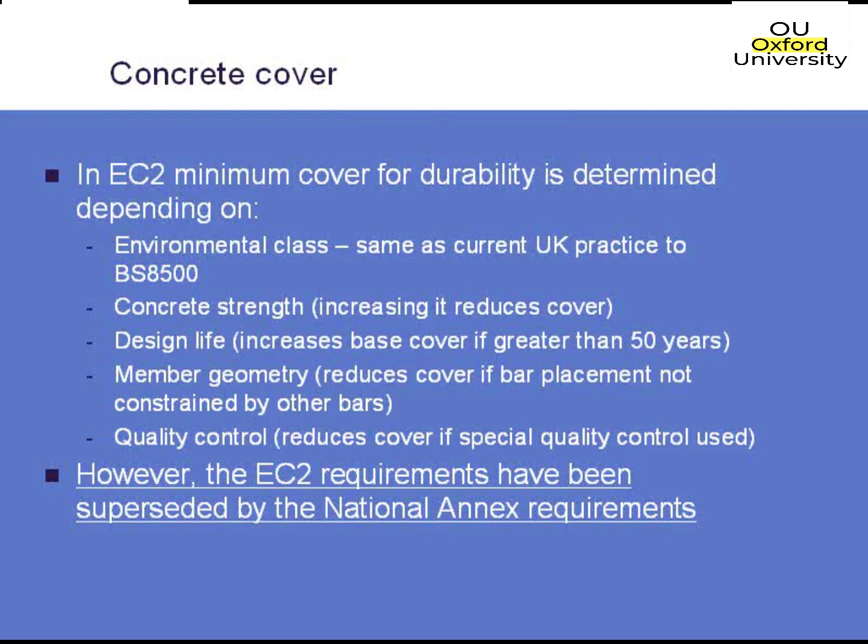The final thing that it will depend on, in accordance with the Eurocodes, is quality control. Basically, the Eurocodes state that if you've got special quality control, you can justify that you can reduce the cover slightly. However, it doesn't actually tell you what special quality control means. So generally speaking, I would recommend that you don't take any advantage of special quality control if you're using this method, and just ignore that.